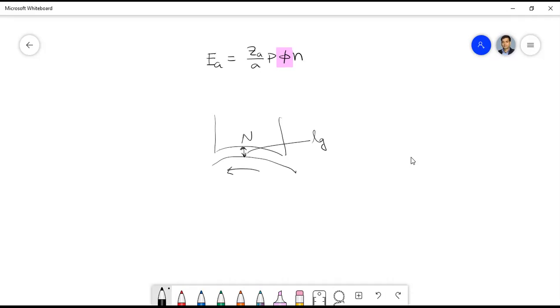This length of the air gap is very important, because it can be different at different locations. Then there may be some reluctance difference, because as you know, flux depends not only on the mmf, it also depends on the reluctance value. So this air gap determines the reluctance.